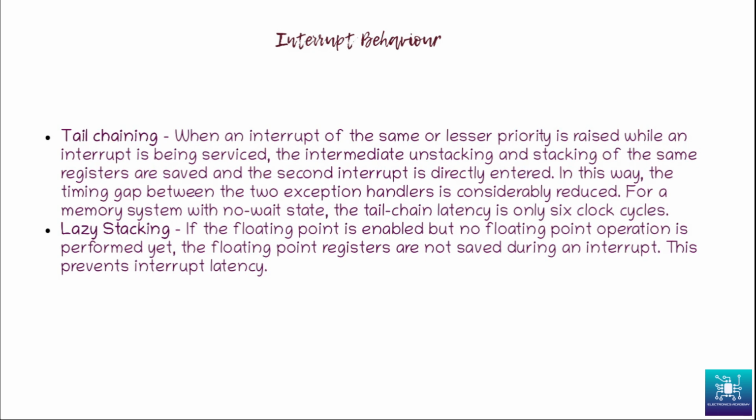Now lazy stacking is again something interesting. Assuming that you have the floating point unit enabled, the stacking and the unstacking process is more extensive than with the floating point unit not enabled, because a lot more registers need to be saved onto the stack for the floating point unit.